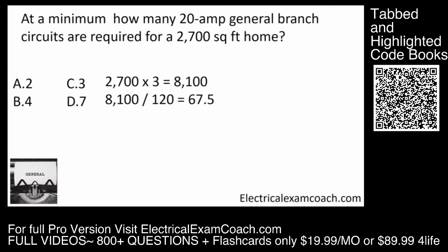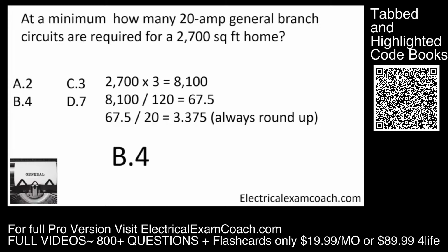Then we're going to take that and divide it by whatever size branch circuit we are going to be installing. In this case, they want to run 20 amp circuits, and that's okay. Here we go. We take our 67.5 divided by 20. That lets you know at a minimum for this home, you must have 3.375 circuits, and we're always going to round up because you can't have a piece of a circuit. So the correct answer would be 4 for this home.